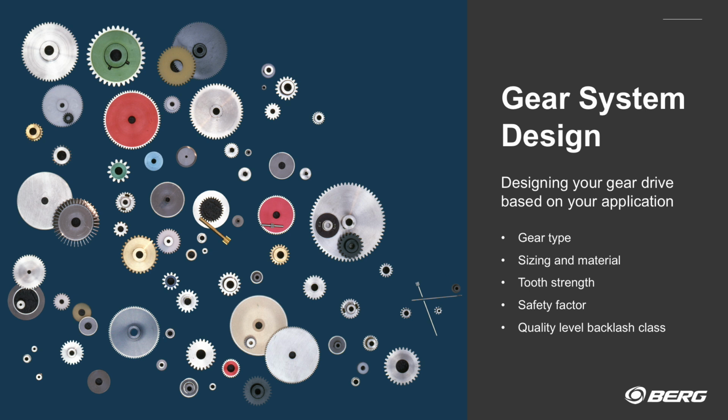Berg manufactures many different types of gears for many different applications. These include straight spur gears, our strongest and most common type of gear. Next are helical gears, similar to the spur gears but quieter running. Bevel gears are used in many applications where the input and output shafts are not parallel. Finally, we have worm gear systems, which are primarily used for higher ratio reductions in relatively small package sizes. All of the gear types that Berg makes are also available with an anti-backlash feature, designed to significantly reduce, if not eliminate, the backlash in the system.